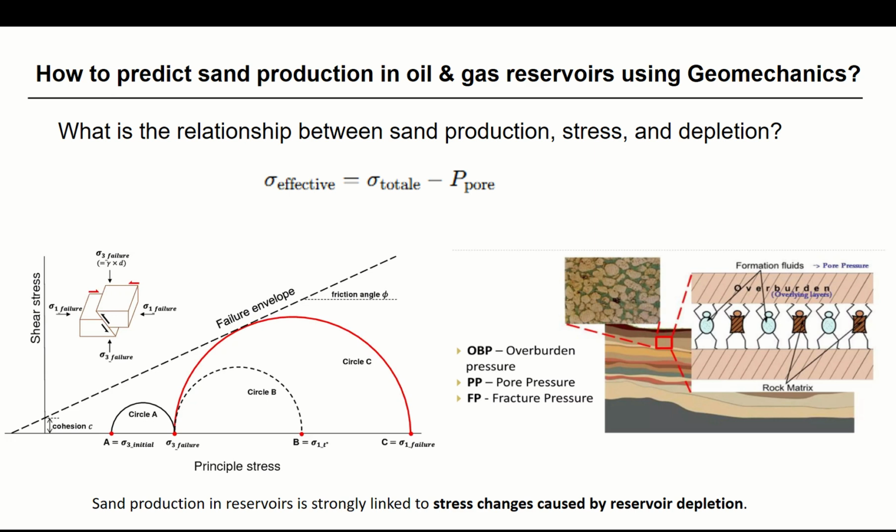This change causes an increase in the effective stress. We say that effective stress equals total stress minus pore pressure. As the effective stress increases, the rock framework is subjected to high loads, meaning here we have a high load from the overburden of the reservoirs.